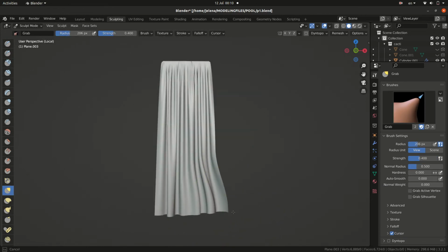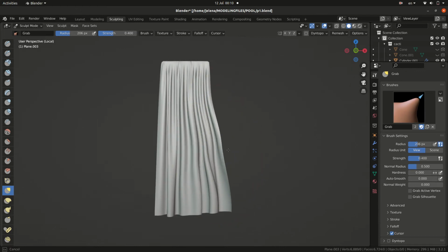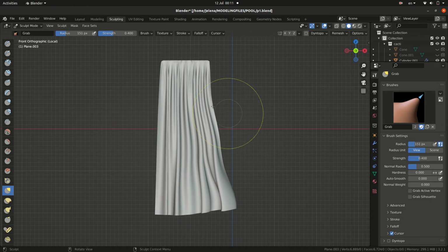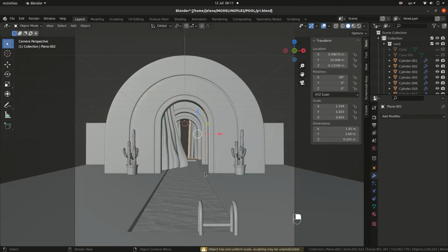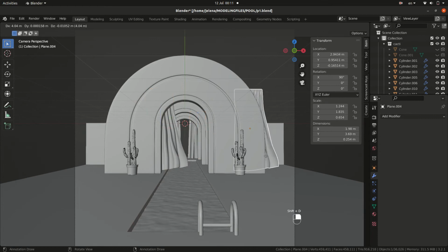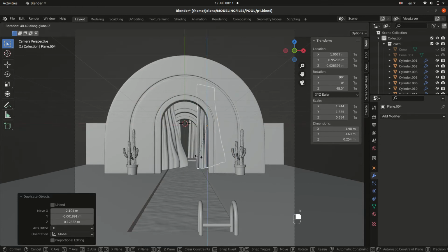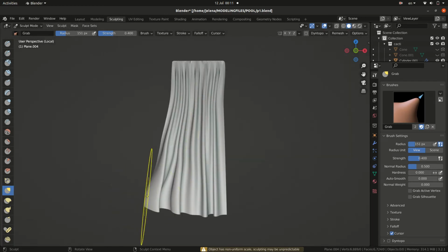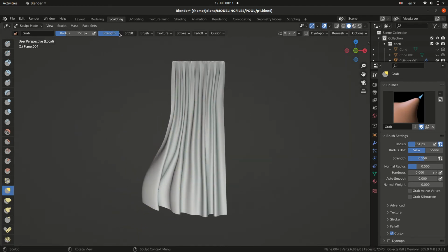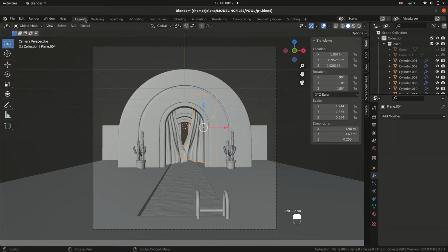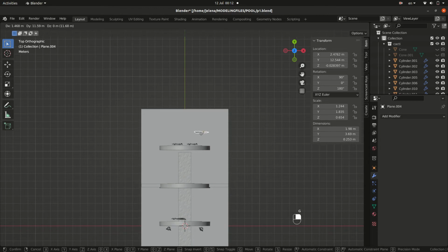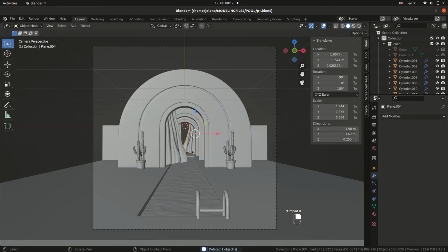And in the sculpt mode, you just want to grab parts and model it like it's windy, something like that. So we want to model it like this. Just add one brush, adjust radius, and pull parts. This is a beginner friendly tutorial, so don't hesitate to work with sculpting. So we're going to duplicate this, rotate, and add some more sculpting because we don't want it identical. Whenever you like, we're going to delete the ones we don't want.